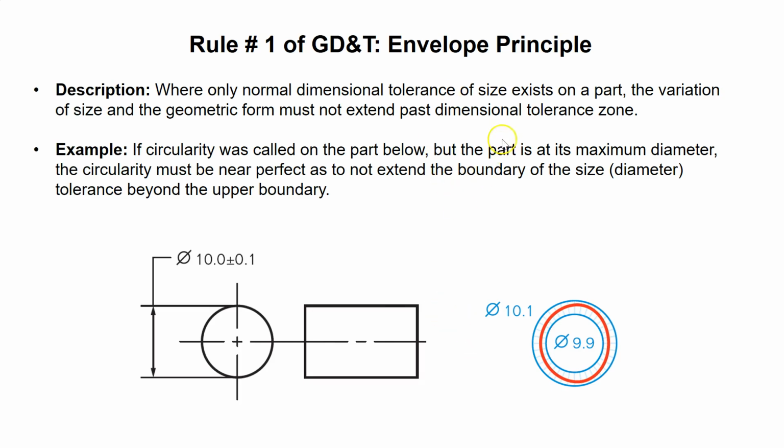So here I want to talk about one of these scenarios, and that is when the cross section of the machined part is not perfectly circular. So I'm talking about circularity here. It is made a little bit elliptic like this. Now my question is this: how far can this shaft deviate from a perfect circle, and how elliptic or different from a circle can it be depending on what size it has been machined?